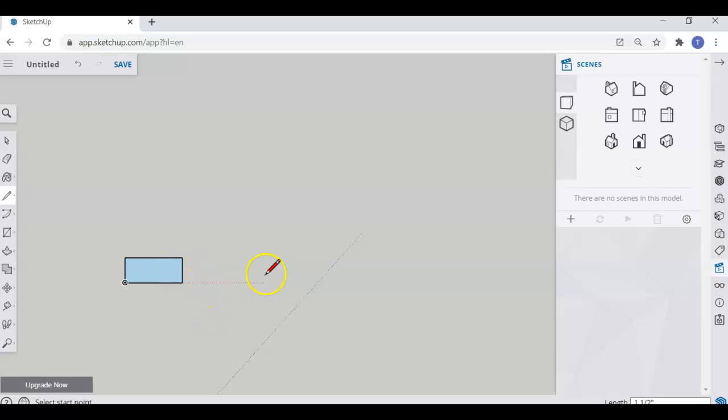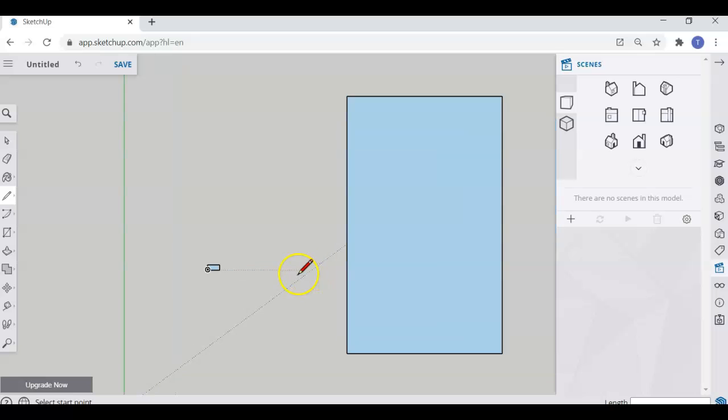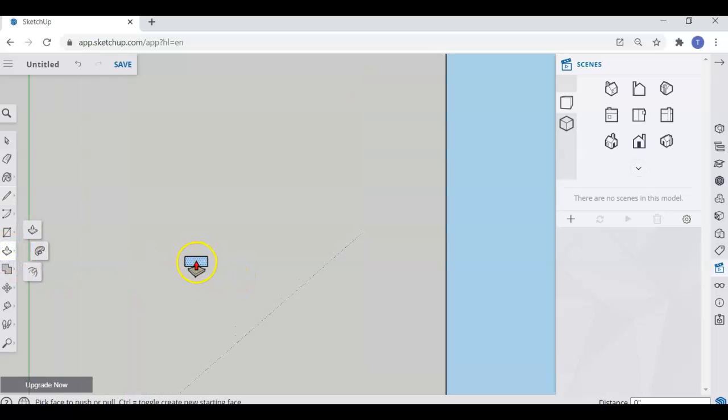All right, now I'm going to zoom out a little bit here, and I'm going to do something real cool, a real powerful tool to do your first little bit of 3D in SketchUp. If you go to this tool here, Push/Pull, it takes an object and extends it into another dimension. In this case, the up and down, going up into the sky. I click there, go inside the space where the blue is highlighted, click, and then I can pull this thing up into the air, or down at the ground. And you can type in the dimension for how much you want it to extend up.